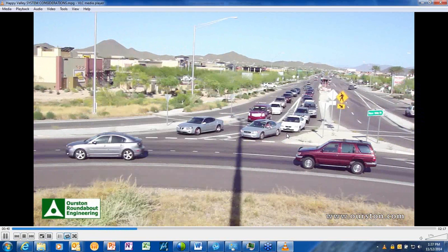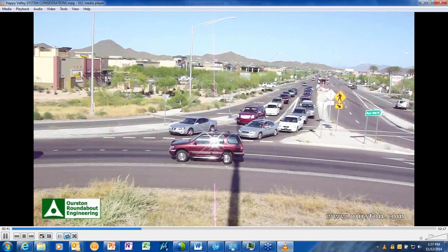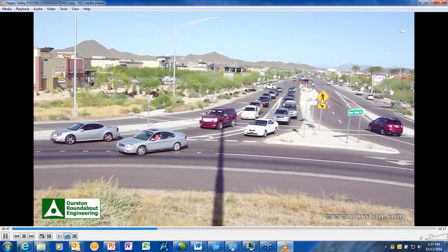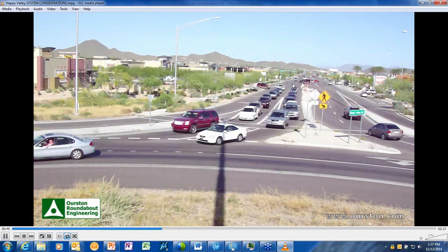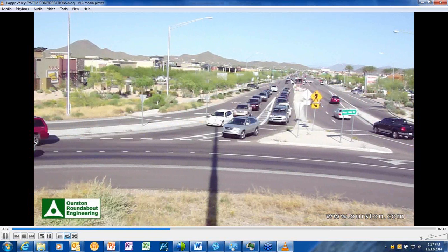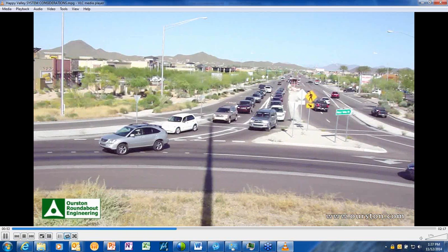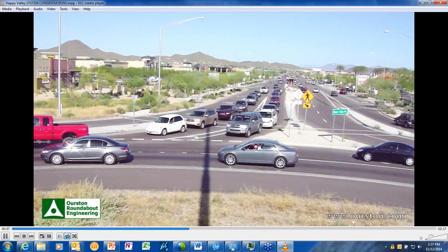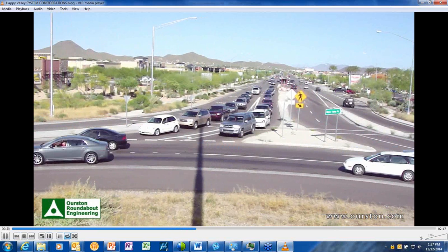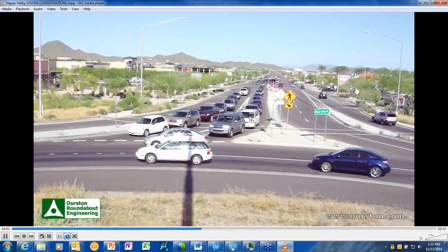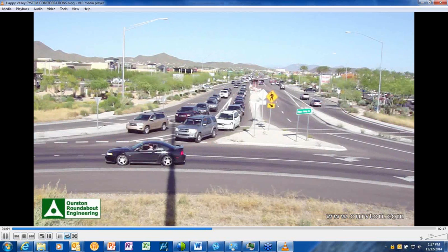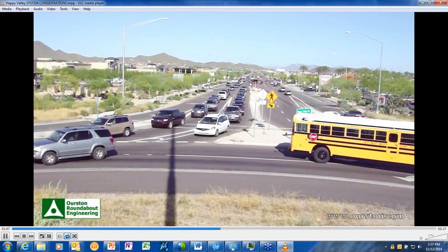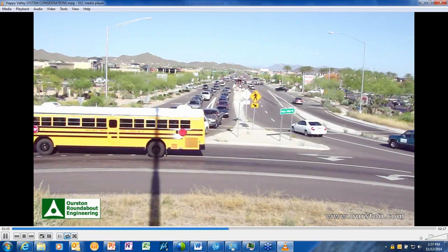You'll see here comes the platoon again from upstream through the signals, and you've got some other side street action coming in between. And so there's kind of a steady approach, but there's still a plug of traffic every 60 or 90 seconds. Lots of left-turning traffic coming towards the roundabout. So this is going to exacerbate the queuing, and it'll back right up because the upstream signal's coming down as this one changes and the green comes in for the east-west direction. We see the queue starting to fill up.